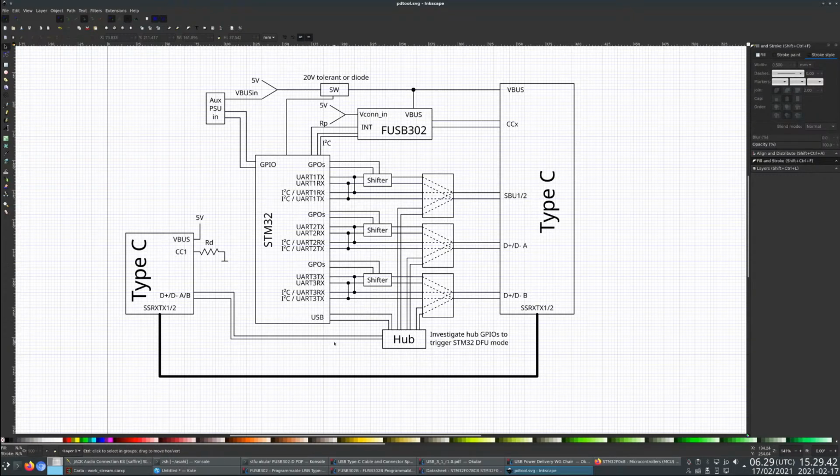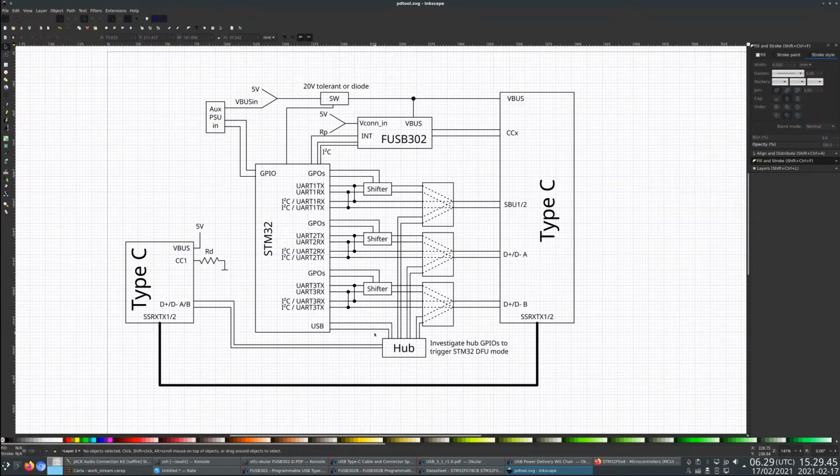I think it simplifies the way of thinking and the amount of things that can go wrong a lot if you just consider this left side to be a host access port for debugging, and you're expecting to first plug this into some kind of host that is sensible, and then this is the target port, and we don't try to pass through anything other than VBus being supplied from here, optionally. I think that keeps the design quite reasonable.